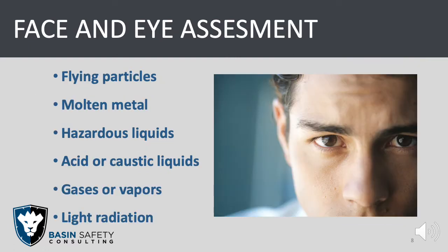So, face and eye assessment. Can things hit me in the eyes? This one, though, to be candid, especially in the shop, people just get complacent because the secretaries are walking through the shop, the HR person's walking through the shop. They're not stopping to put on safety glasses. So sometimes our workers are just like, if they don't have to do it, I don't have to do it. What's the big deal? But if you're working around anything with metal, hammers, saws, grinders, and really anything that can have chipping or material being blown into the air, working with air hoses, dust can get in your eyes. Get in the habit of wearing safety glasses in the shop. I will say that's important.